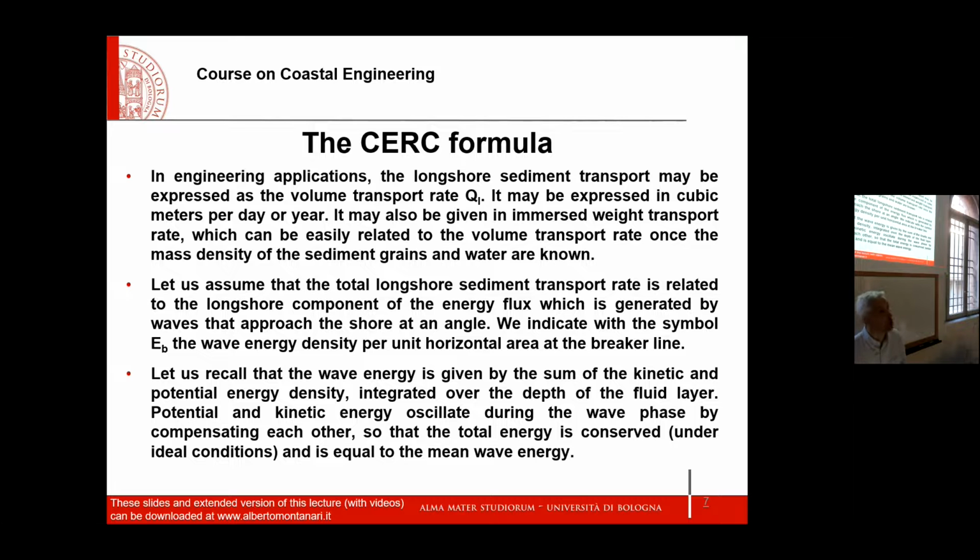Okay, so let's now find an analytical relationship then, which gives to me the volume of sediment that is transported per unit time. I already mentioned the basic assumption. This volume is proportional to the energy of the waves. And it's written here. And this formula that we use that is based on this assumption is called the CERC formula, or CERC, okay? And I don't remember the meaning of this acronym. We will go to the web pages, it's written there. This is a formula that is widely used.